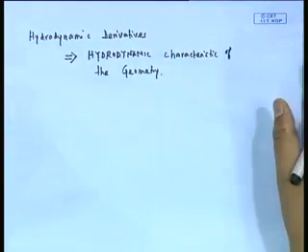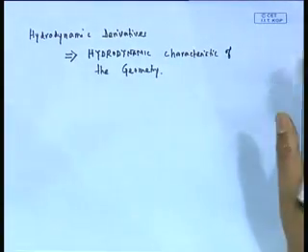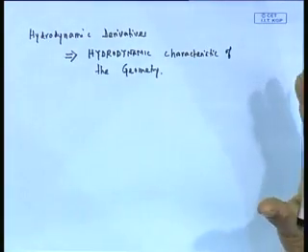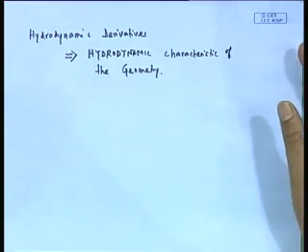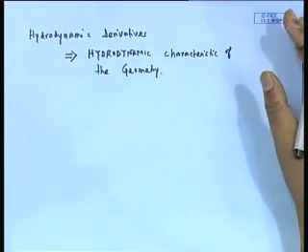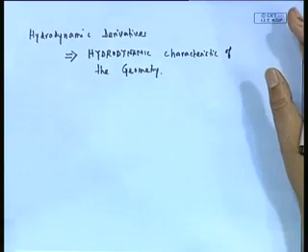Why I am saying this, because just like certain hydrostatic parameters for a given geometry, remember when I gave the example of KB at 5 meter, at 5 meter draft the underwater hull geometry is fixed. So, for that geometry there is a fixed location of center of buoyancy.